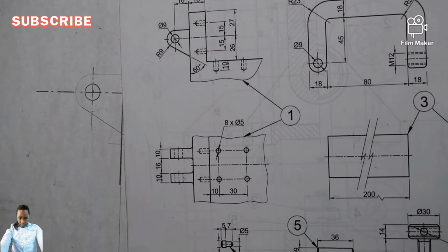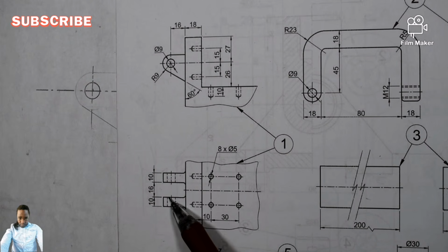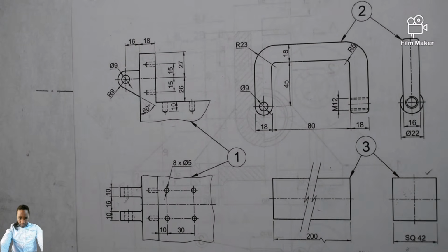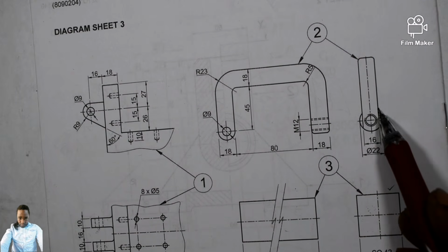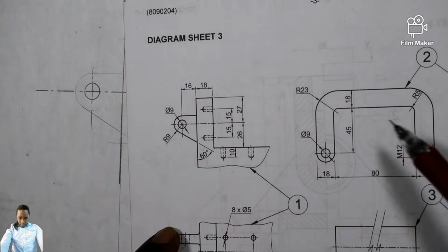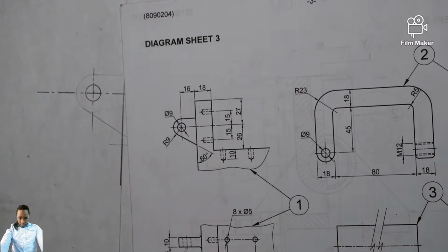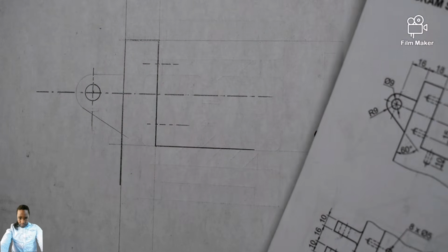Understand? And the thickness of item 2 must tally with what? With this thickness. You understand? So the set is 16 millimeter, from here till there is 16 millimeter, which corresponds with what? With your item 2. Check the thickness of item 2, from here till there is 16 millimeter. So which means indeed we are going to draw item 2 right here. Supposed to be making a clamp like this. Remember, they told you that it's a G clamp.